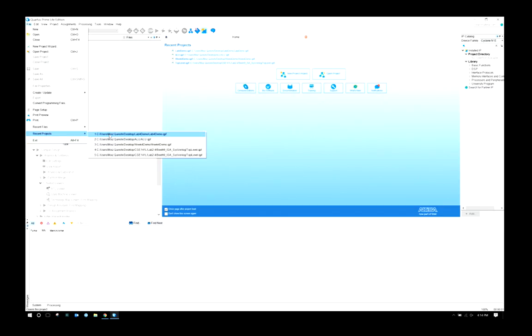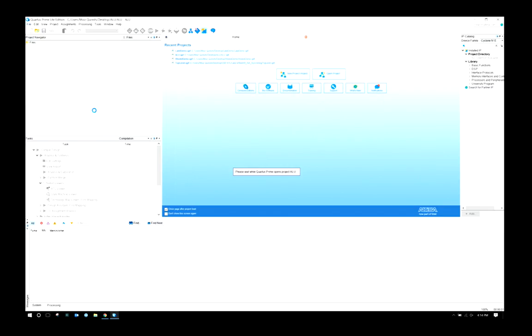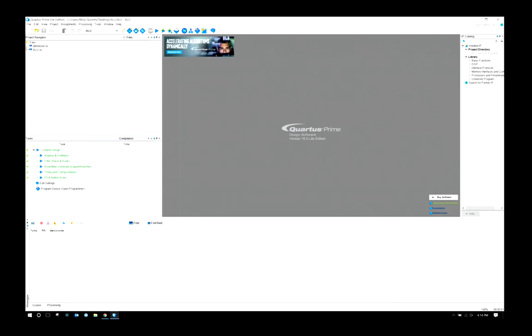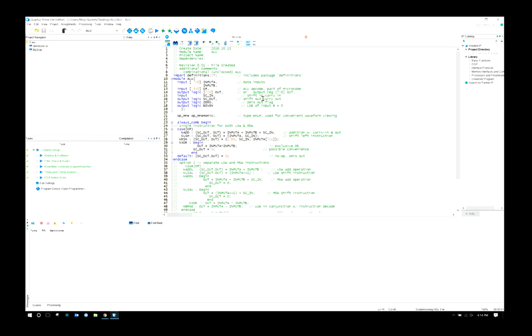I already created one with just the ALU in it. So you're going to code out your ALU module, and you're going to make a project. What I recommend is you make a Quartus project for each of your modules for this lab. You can just keep it separate right now, and then when you get to Lab 4, you can have just the project that ties it all together. So make 3 projects for your ALU, reg file, and your instruction ROM, PC, all that stuff.